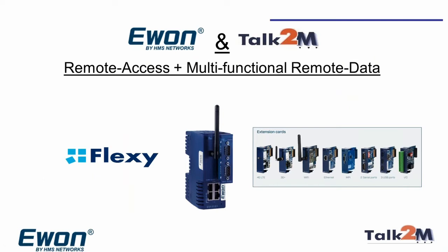So here is the Flexy 205. This particular model in the Flexy range, there are 4 within the Flexy range, but this is by far and away the most popular. It has a base with 4 Ethernet ports, and then you have 2 slots at the front here, and you can put any number of cards in them. You can see an array of cards on the right-hand side that you could slide into these slots. So it's a modular system with core functionality within the base, and then additional functionality provided by the plug-in cards.